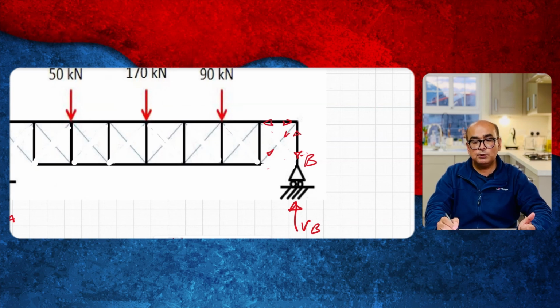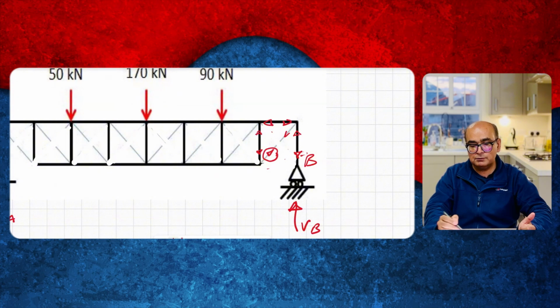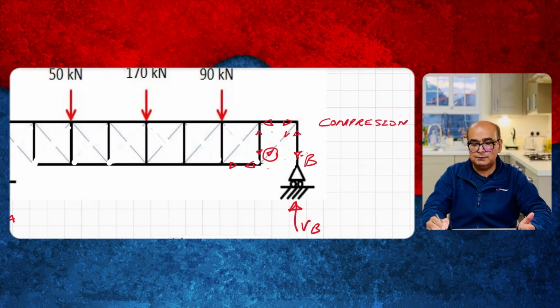And again, if it is pointing upwards over here, the load should go downwards. It means that there will be compression over here, and in the same way we will continue. Now all members at the bottom side will be in tension and the top side will be in compression. So remember that we will have compression at the top and tension at the bottom.